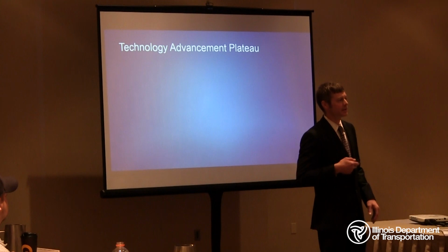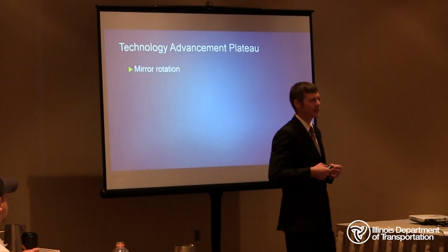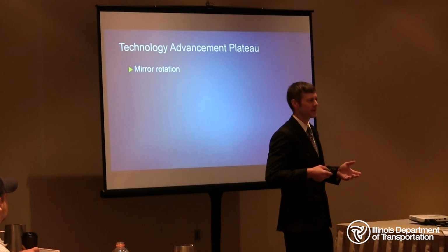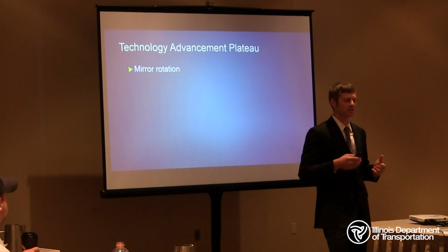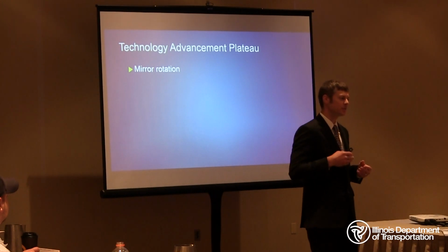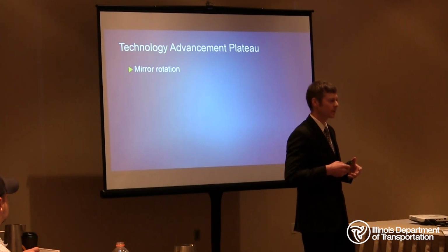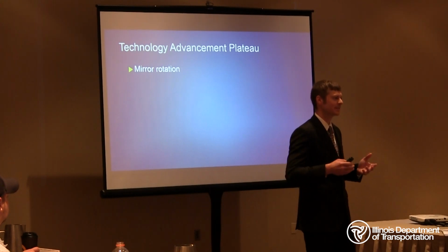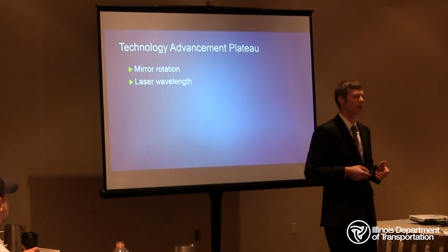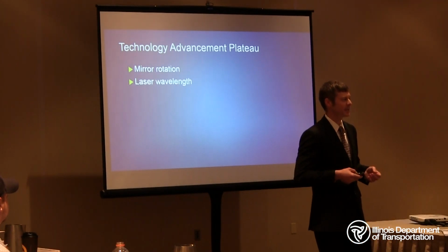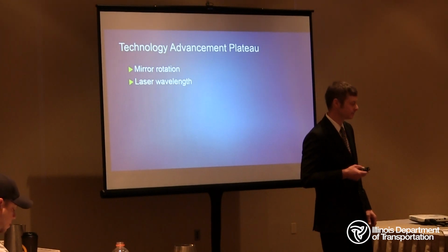In regards to the technology advancement plateau, they stated that mirror rotation has currently been maxed out at 250 times per second, and in fact, most data collections are occurring at a slower rate of speed because at 250 times per second, the point cloud starts to introduce a lot of noise or extraneous data that really just isn't there. They also mentioned that the current laser wavelength has been the industry standard for the past 8 years, and it's giving us the best return for hard surfaces.